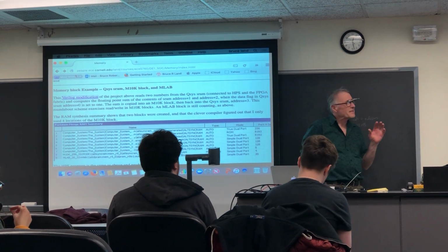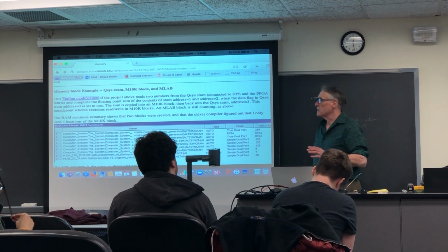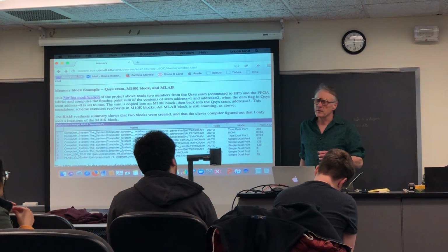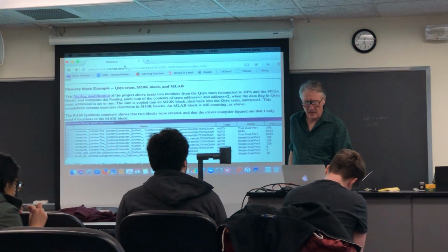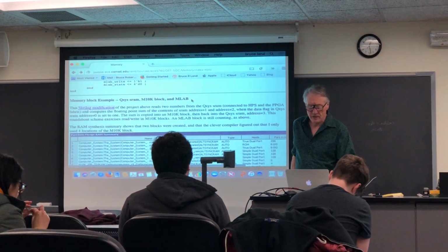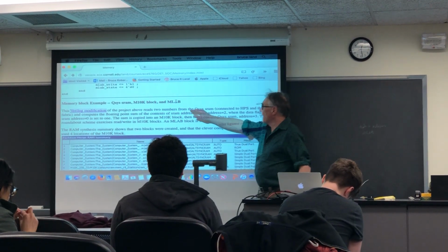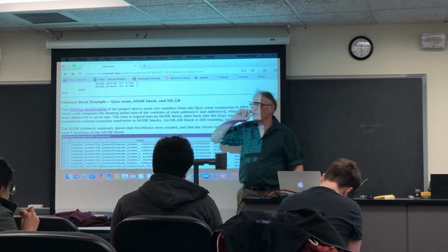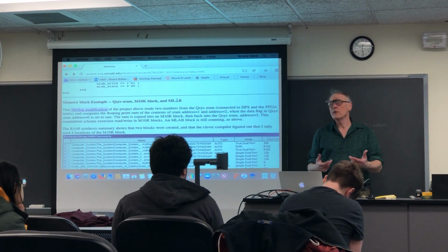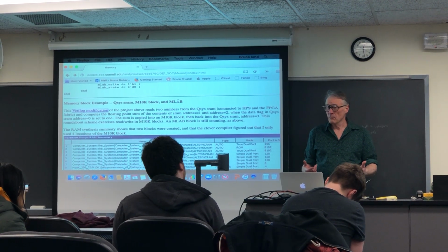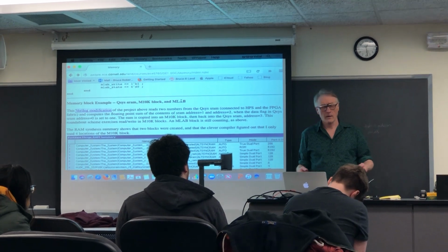MLab has a slightly different readback characteristic than M10K in terms of asynchronous reads, but they're basically the same, except MLab blocks are smaller and maybe better suited for small register sets like a CPU register set, where you don't want to use up a whole M10K block.